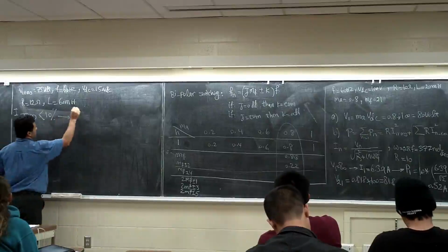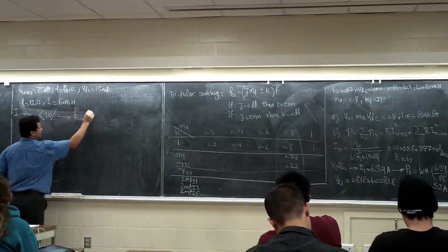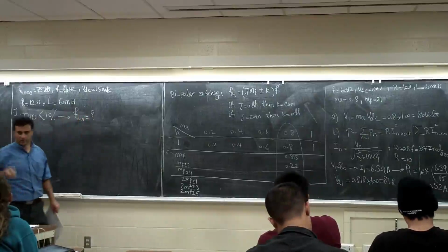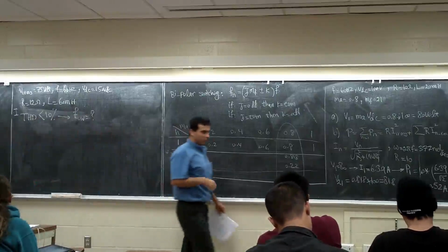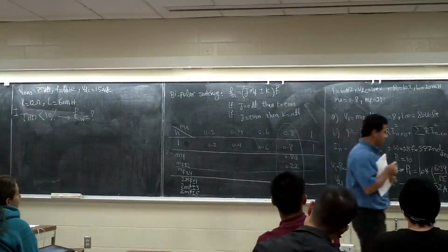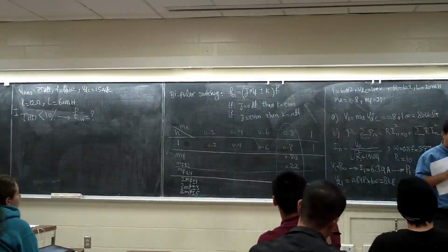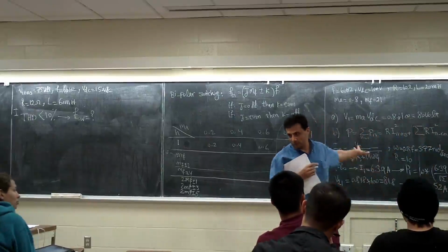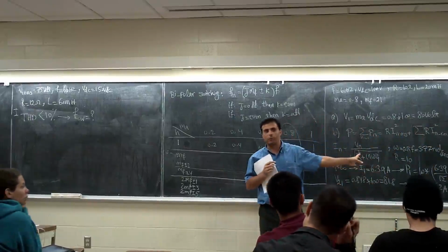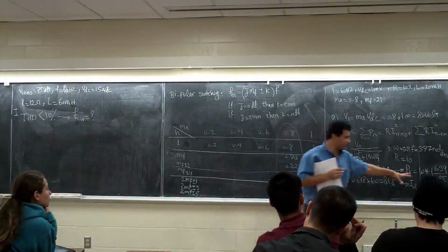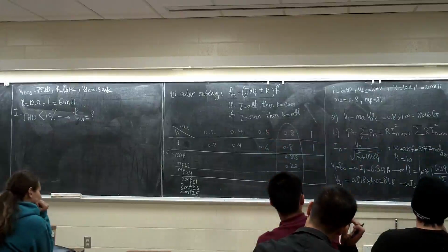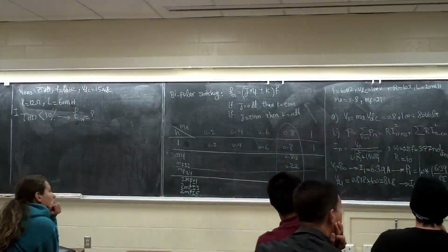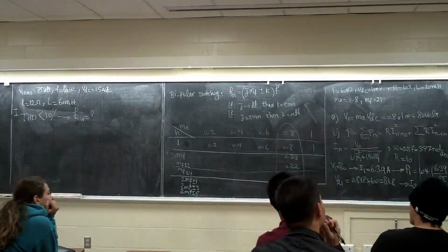What frequency should I go? What is the FSW? Or FS, I call it FS, previously I called it FS. What switching frequency should I go? You can see here, what did I say here? I said if I double the switching frequency, MF was 21, if I make the MF 42, my THD instead of being 8 point something, most probably it's going to be half almost, right? It's going to be 4%.